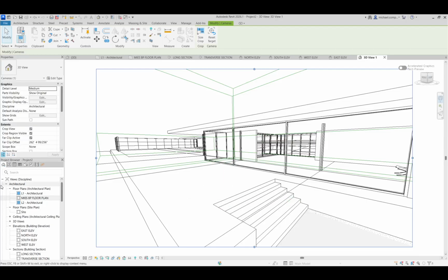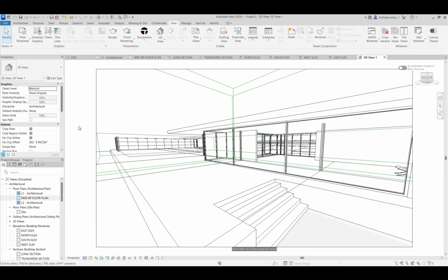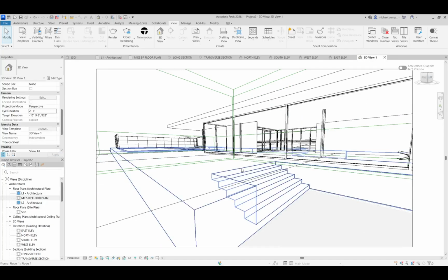There's no architecture below me. I need to make sure that my eye level is 5'6", but I need to make sure I'm, again, on the ground, not floating in the air. So I scroll down the properties box. Look, my eye level is 5'6", but relative to level 1, which is 3 foot above the ground. So I'm going to change that to 2'6", which will keep my eye level still at 5'6", but lower my whole body down to be on the ground. And now I'm ready to walk up the steps.